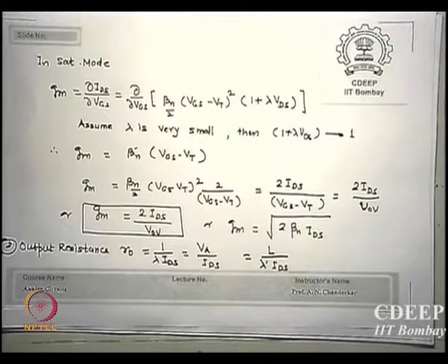In real life VT is not a constant quantity. So when I differentiate with respect to VGS, VT also has to be differentiated, then it becomes more complicated expressions and hand solving sometimes becomes difficult, and SPICE does this automatically, you do not have to think. The best thing about SPICE is it does not allow you to think, and that is good for us.